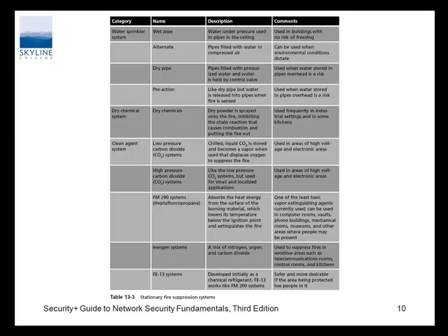How would they drain it? You have to turn the pressure off and with a bucket, open it up and just drain the water out of it. So when I stand up, blow the sprinklers and drain. Yeah. Now, a building like this is going to take some time because there's a lot of sprinkler heads.